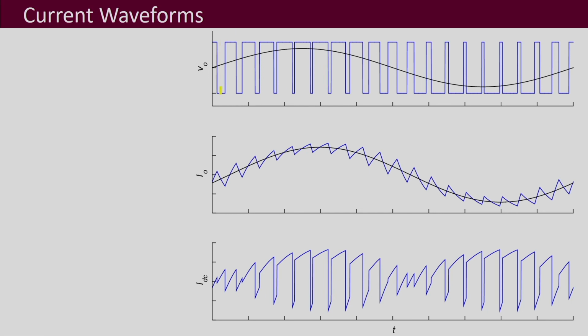So, this is the instantaneous output voltage waveform. This is your VO, which varies from plus VDC to minus VDC, and this is the 0 of it. And this is the VO bar, the average of it, what we saw over switching time periods.